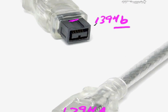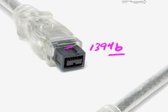And then another kind of cable you might see looks amazingly like this. It's almost identical to this 1394B look that we have, except that the notch, the key up here at the top, is a little bit wider, and that would be what we call a 1394B beta cable. And that means that it will only communicate with other 1394B devices or ports.